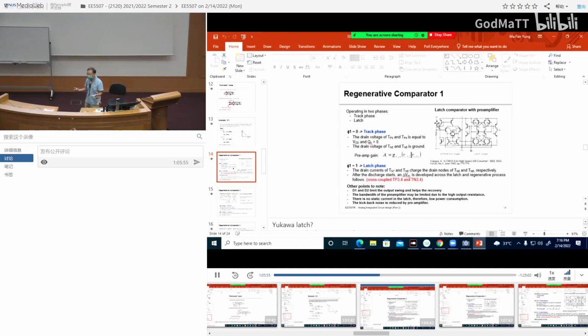The good discipline is input always on the left, output always to the right, all other control signals top and bottom. Power supply always comes from the top, ground always from the bottom. If you draw a systematic circuit, it is easier for people to read. I've seen people draw circuits with inputs coming from all over the place, and you have to hunt for where the input is.